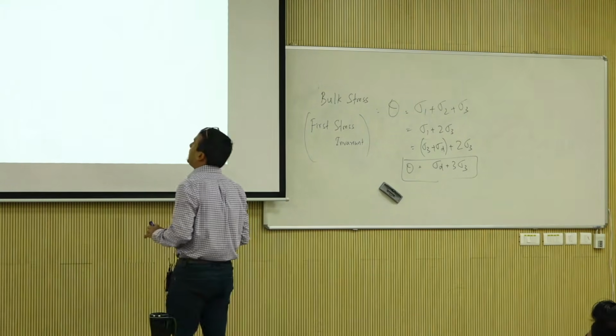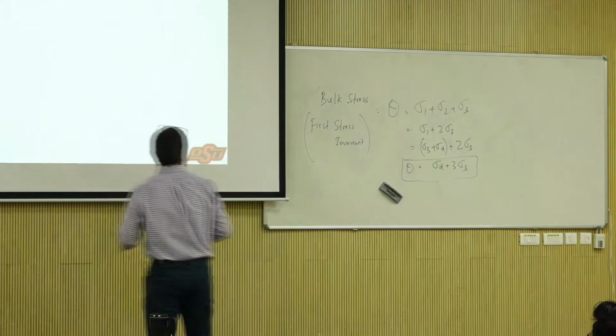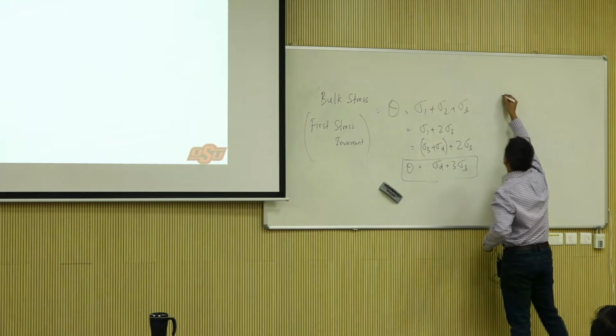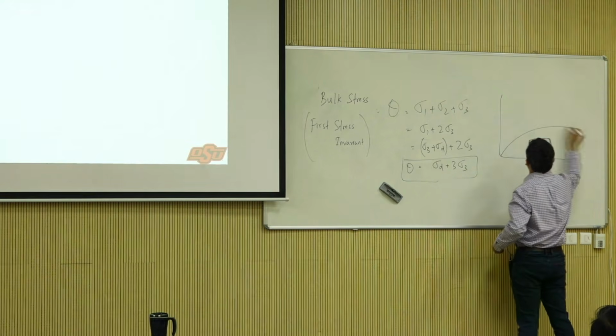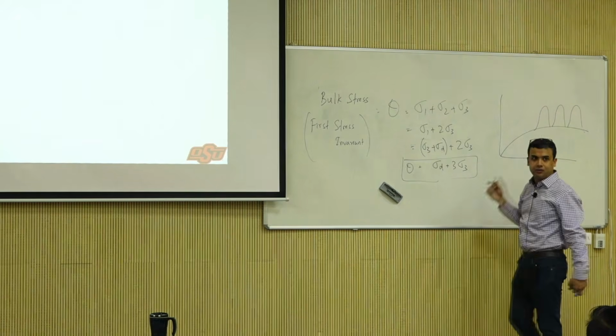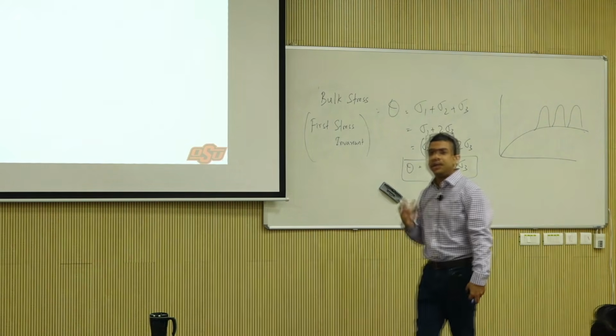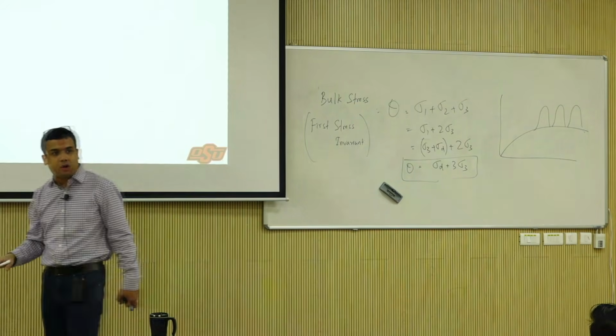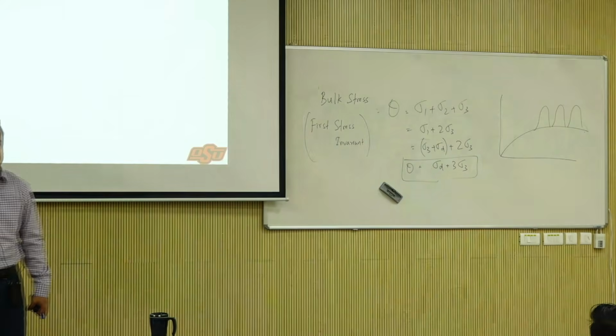Okay, factor of interest. Repeated loading. I accidentally wiped that, but you saw that in the same plot. So repeated loading gives us information about both resilient modulus and permanent deformation.